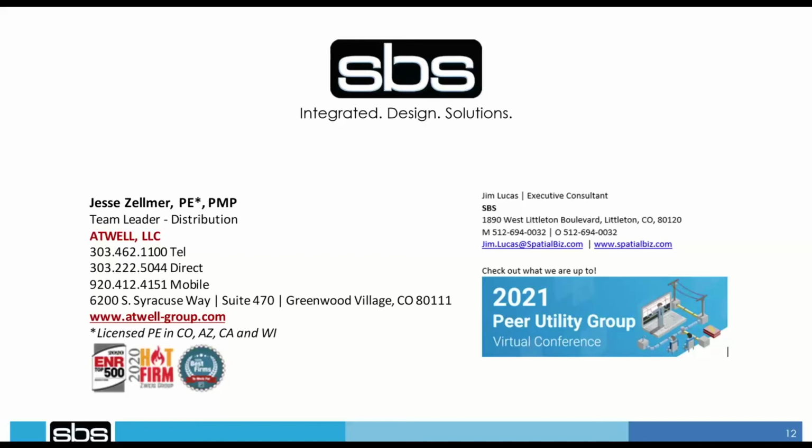Another great feature for us on these projects is automatic callouts. When we select a certain type of crossing, like I mentioned before, or a piece of equipment, and that changes, these automatic callouts that pop up are automatically numbered, so it could be junction box 2 through 29. Those are automatically generated for us.